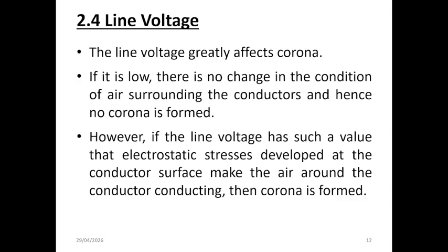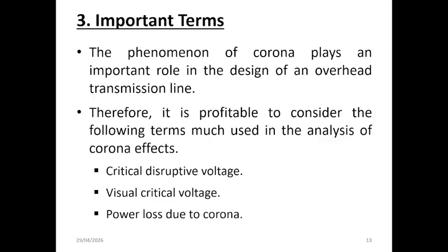Therefore, higher transmission voltages increase the probability and intensity of corona, making voltage control and proper line design essential in transmission systems. So the phenomenon of corona is an important consideration in the design and performance analysis of overhead transmission lines.